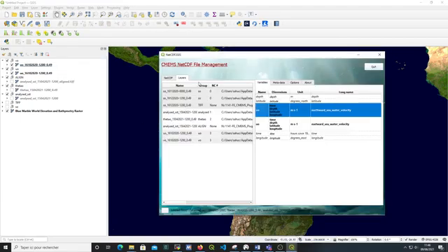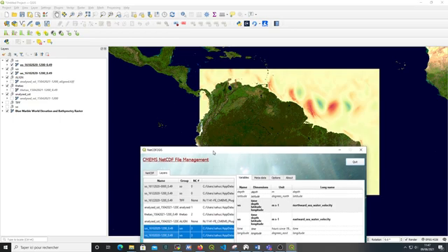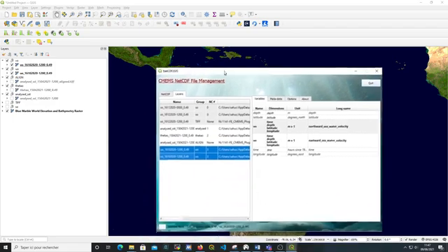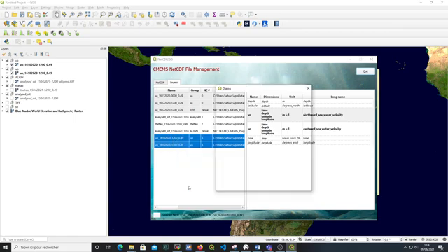If we go back to the plugin, we go to the Layers tab, and here we are going to draw a vector field of these two components, eastward and northward seawater velocity, to have a vector field and not scalar fields corresponding to one to the U0 variable and one to the V0 variable. So you select your two layers by pressing the Control key on your keyboard, right click on the two layers and select Vectorize.